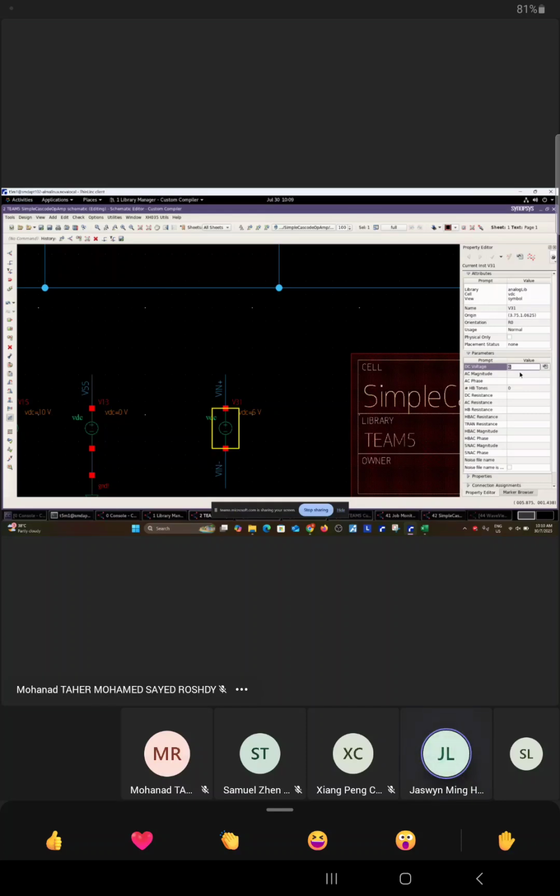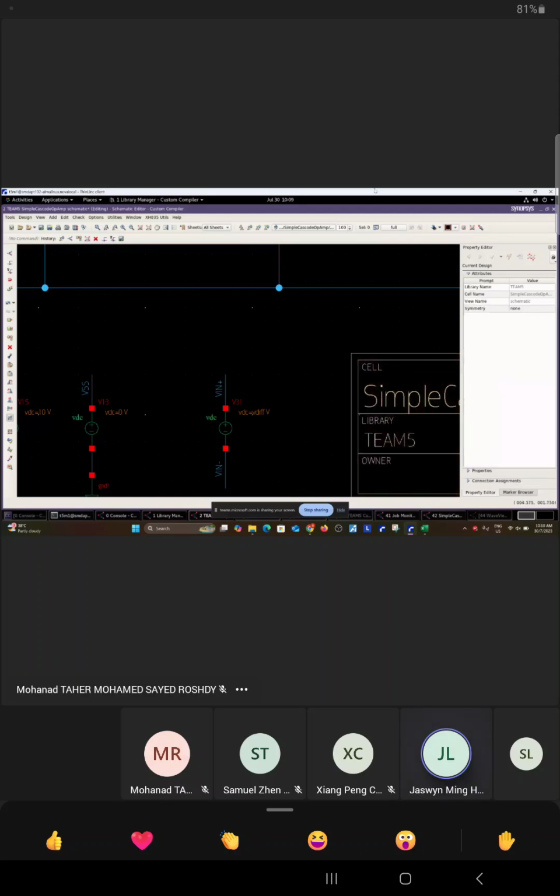Maybe it's both, because if you do negative feedback, if your output is higher than your V in positive, then you can correct that. So maybe you can sweep from -5 to 5. I doubt the output will actually swing that much, but you can just sweep like that. So here you can put a VDIF, while keeping our VDD at 10 volts. Yes, correct. You can do a double sweep, meaning a nested sweep, but let's do one scenario first.